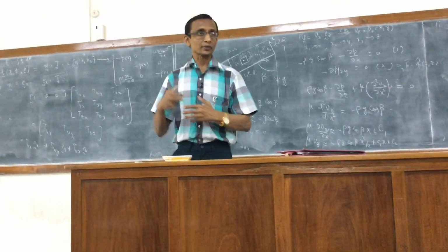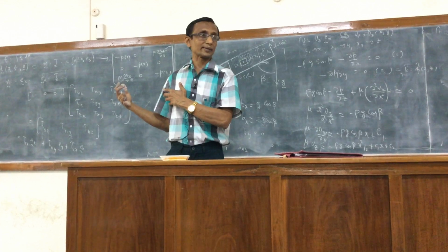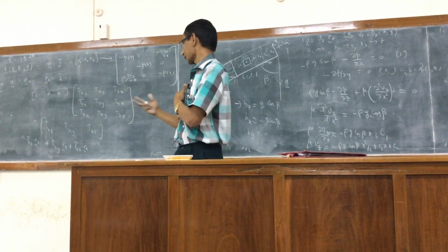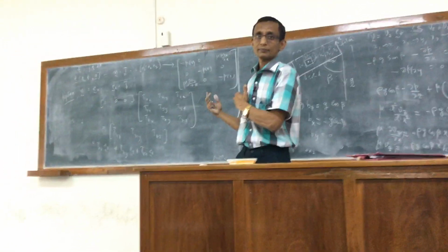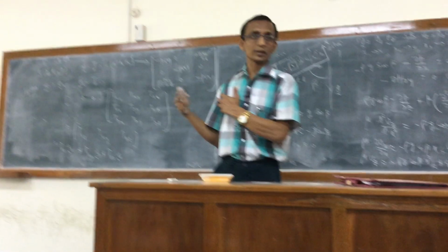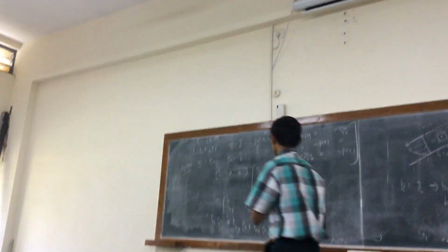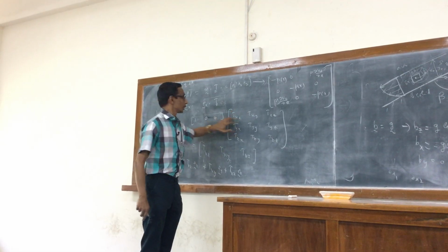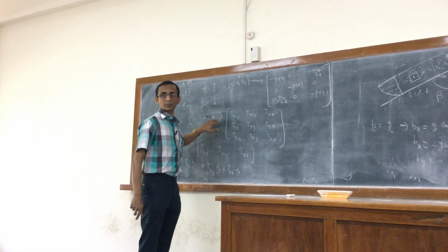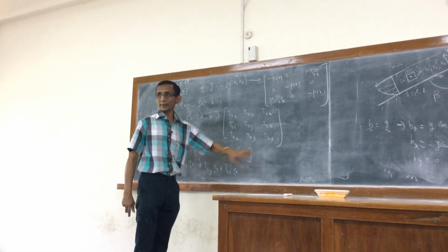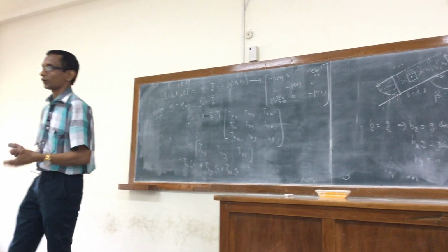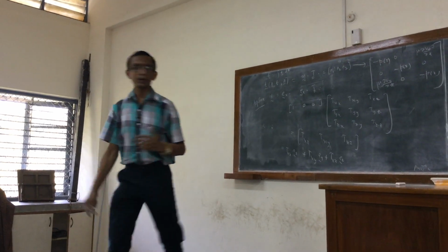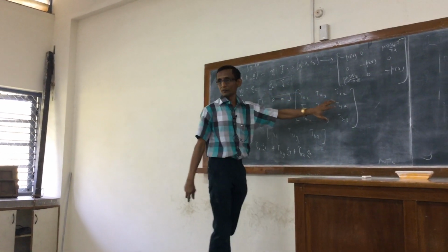It captures three of the components of the stress tensor: Txx, Txy, and Txz. You can easily now infer that when it is capturing the first row of the stress tensor, if we were to take Ey, then it would take the second, but you know that whatever may be the normal, you can easily calculate by calculating the dot product in this way.